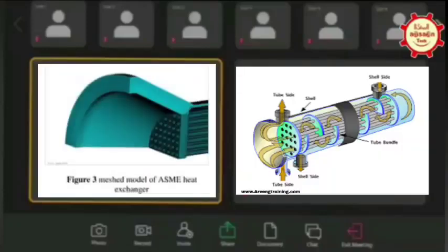Not to undermine TEMA. Okay, Atul, I think you do many heat exchangers. Which one do you use maximum? Always ASME, because TEMA gives less. So almost everybody now is going with UHX. Okay, Abhishek, we are following ASME. We can't go for another standard also. It will always be ASME.